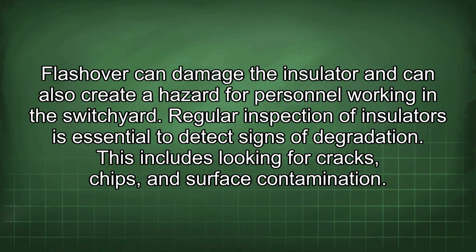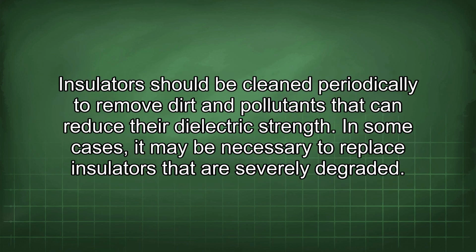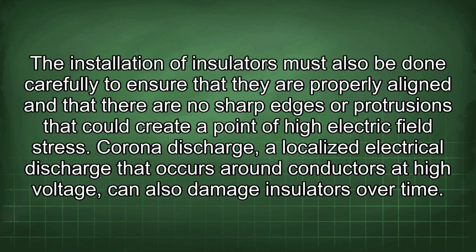Regular inspection of insulators is essential to detect signs of degradation. This includes looking for cracks, chips, and surface contamination. Insulators should be cleaned periodically to remove dirt and pollutants that can reduce their dielectric strength. In some cases, it may be necessary to replace insulators that are severely degraded. The installation of insulators must also be done carefully to ensure that they are properly aligned and that there are no sharp edges or protrusions that could create a point of high electric field stress.